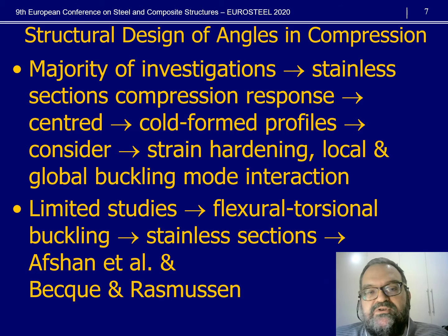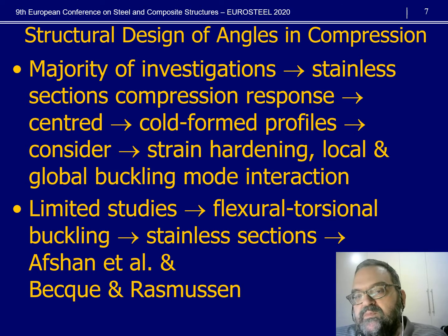We could see that the majority of the investigation involving stainless steel compression response was centered on cold-formed profiles that considered strain hardening and the local and global buckling mode interaction. But we could see that there were very limited studies involving the flexural-torsional buckling of stainless steel sections, as it was reported by Ashraf et al. and Becque and Rasmussen.